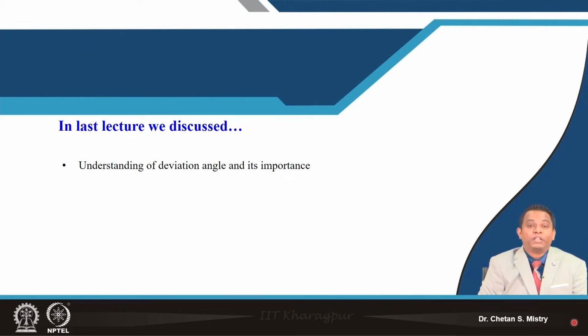We will be discussing all this in detail when we discuss the design for a low speed compressor. We will discuss this for a high speed compressor. We will also discuss it for a contra-rotating configuration, and equally for industrial fan design. But at this moment we can understand that we need to take care of the change of incidence angle and the change of deviation angle during the design stage only.